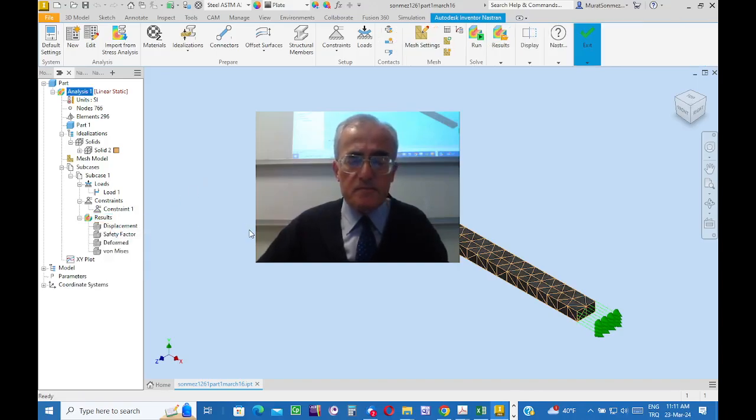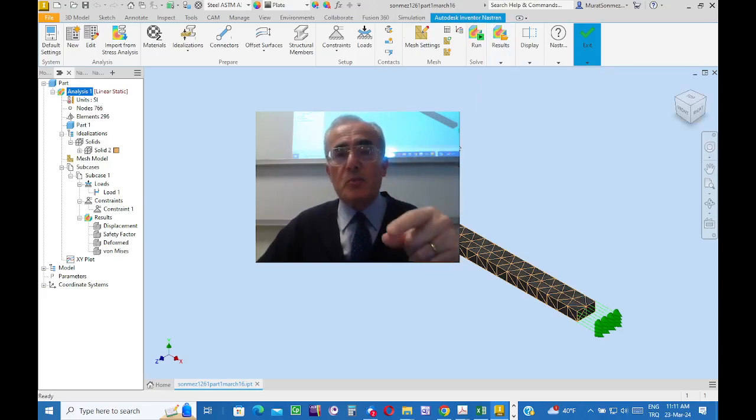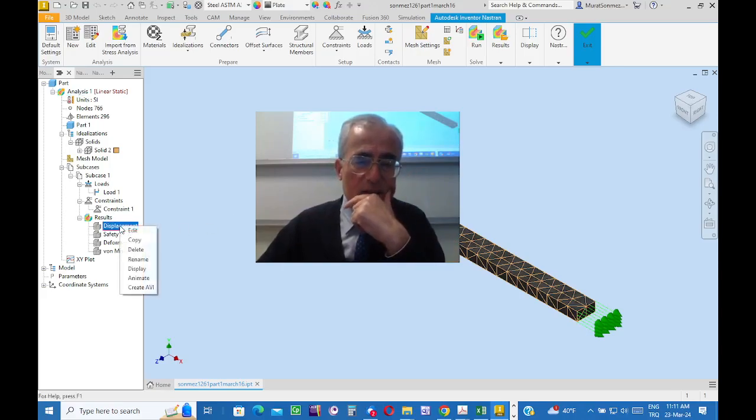After saying load, if the folder in which the software keeps the data is still at the same address, then Nastran can automatically gather it. But if you change the address of that folder for any reason, then after clicking on the load button, in the search dialog box you can indicate the folder, indicate the log files. Okay. And then, after having the results active to have a look at, right click the mouse and select the display option